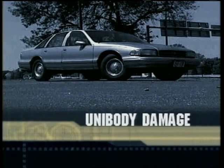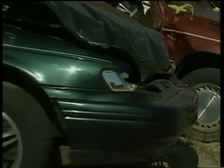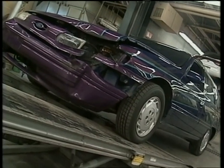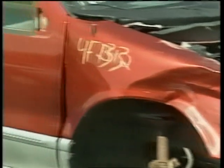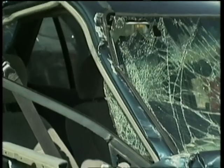Here are the typical effects of damage to a unibody vehicle. Frontal unibody damage results from a head-on collision. In minor impacts, the bumper and frame horns are pushed back. As the collision force increases, the side rails and radiator core support are involved. With greater impact, the fender will contact the doors. The front cross members may buckle, or the body pillar will bend and drop the doors down.